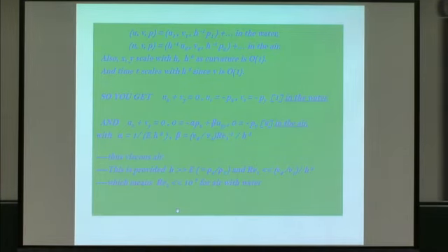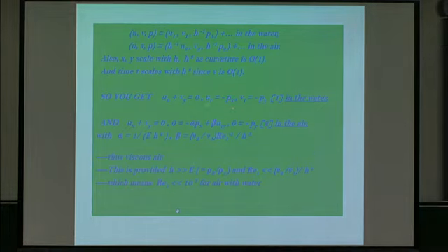So let's have a look here. We've covered those four lines already. What we get in the water is the equations of unsteady potential flow. So it's full continuity, and then acceleration terms u_t, v_t balancing the pressure gradient, dp/dx, dp/dy. So from that in the water then we're going to get Laplace's equation for u, v and p, as you might expect.